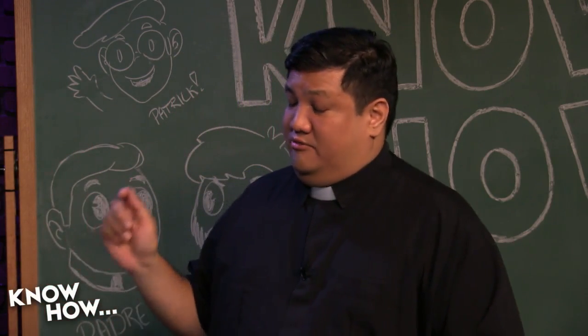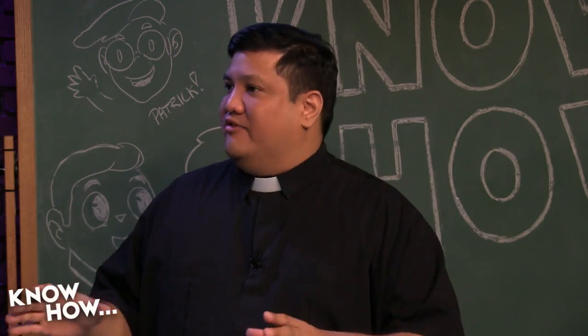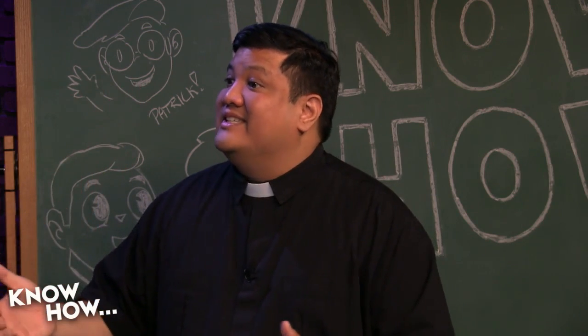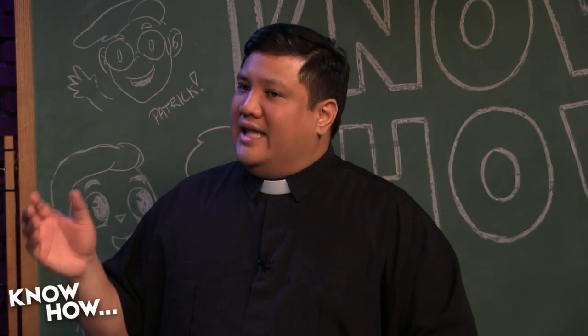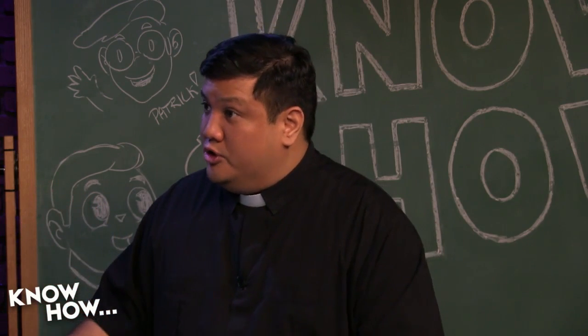Then there's the SRAM, which is static random access memory. That is volatile. So if I unplug the power, the flash is safe, but that SRAM gets wiped out. And what is usually saved in the SRAM? That's the computer's memory, the system memory. Any of my variables, anything that changes, that's stored in SRAM. And it's useful because it's fast.